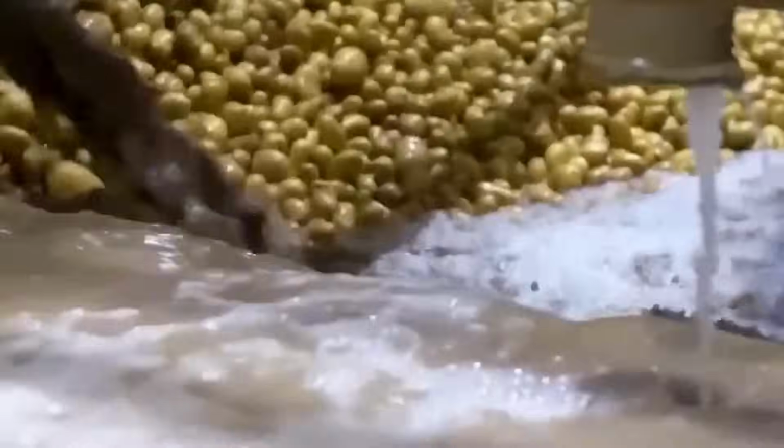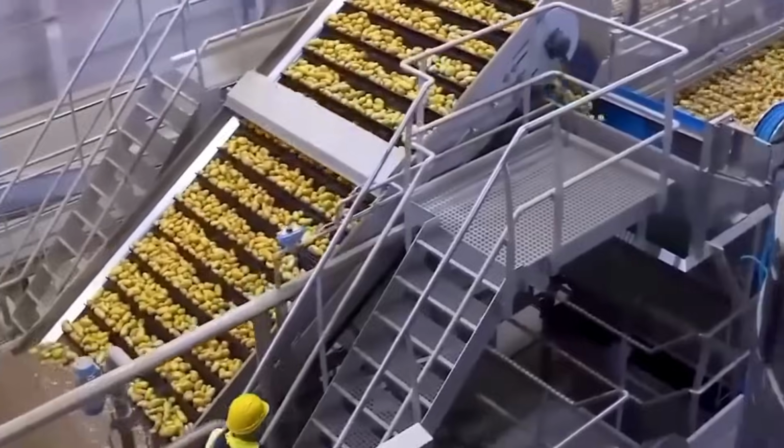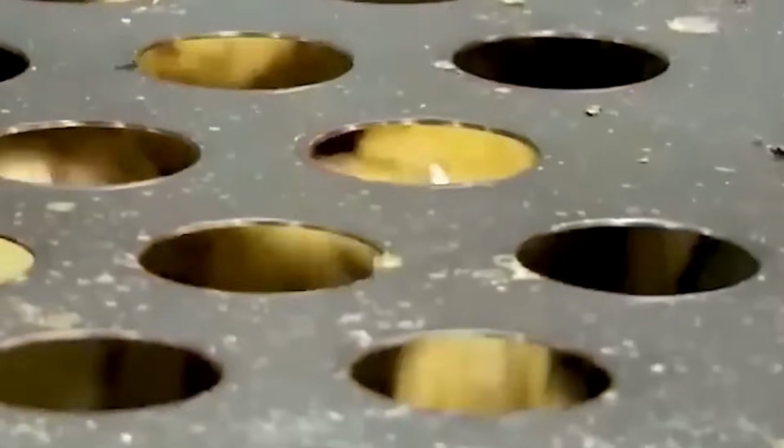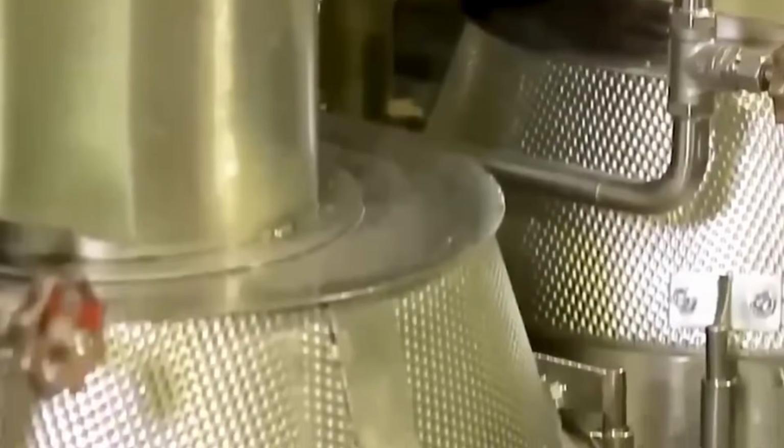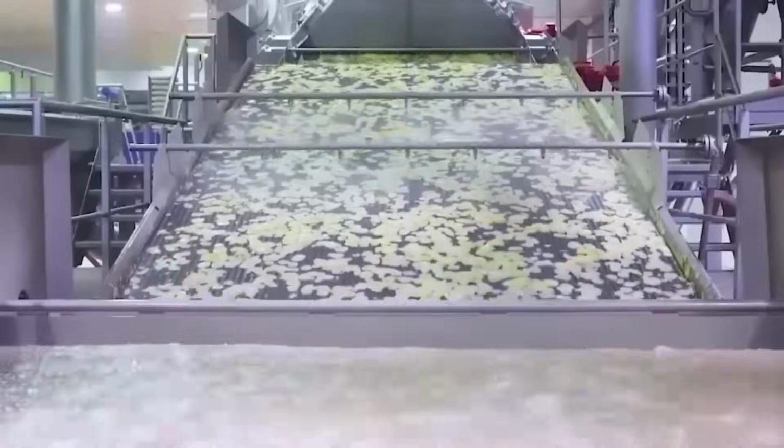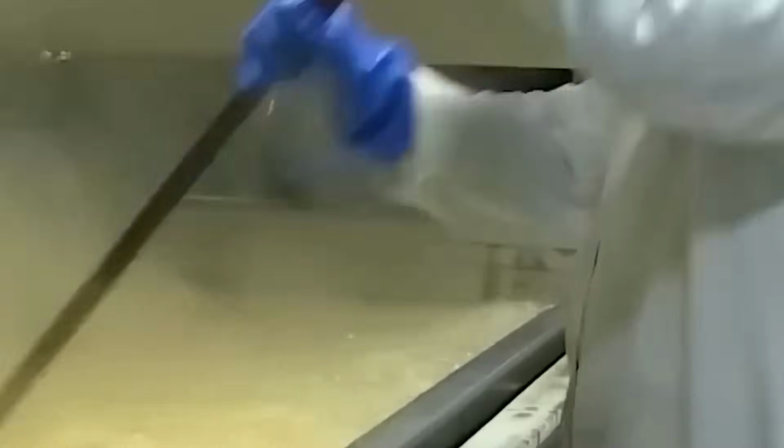After cooling, the chips enter the seasoning system. A vibratory conveyor feeds them into a rotating drum lined with helical flights to provide continuous tumbling. Liquid or powder seasoning is applied via spray bars or auger-fed dosing units mounted above the drum. Liquid flavor systems use oil-based carriers with atomizing nozzles to create fine, even coverage. Powder seasonings are dosed based on real-time weight feedback to maintain precise seasoning ratios. The tumbling action ensures uniform adhesion of the seasoning to the chip surface.